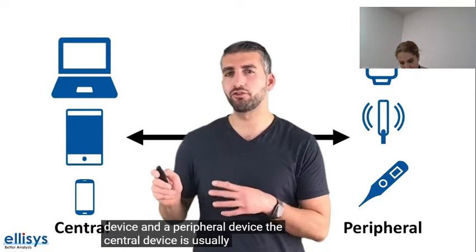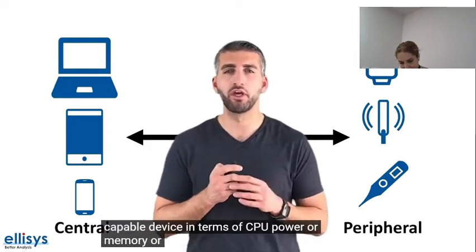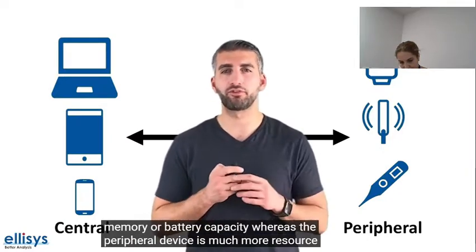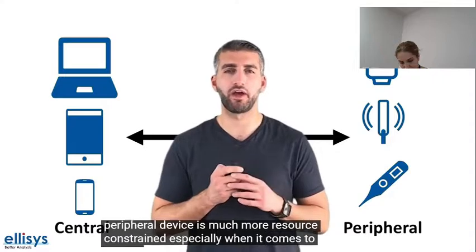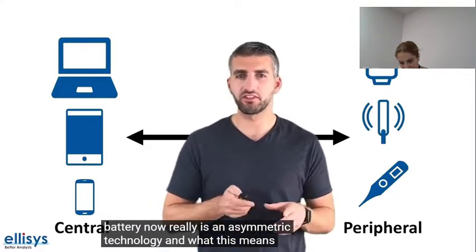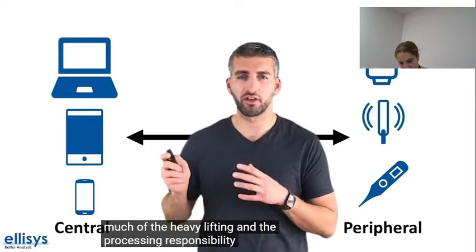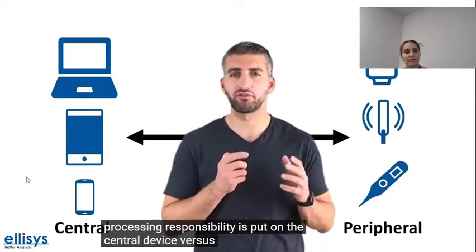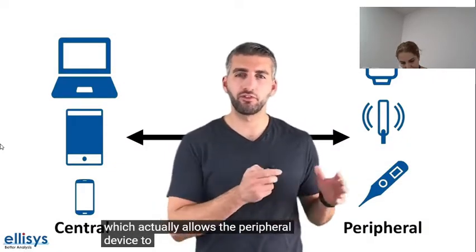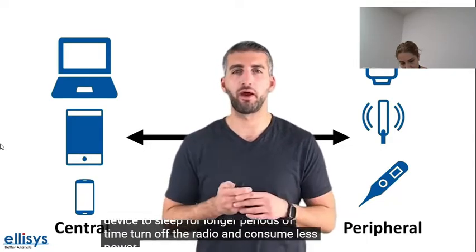The central device is usually the more capable device in terms of CPU power or memory or battery capacity, whereas the peripheral device is much more resource constrained, especially when it comes to battery. Now, BLE is an asymmetric technology, and what this means is that much of the heavy lifting and the processing responsibility is put on the central device versus on the peripheral, which actually allows the peripheral device to sleep for longer periods of time, turn off the radio, and consume less power.